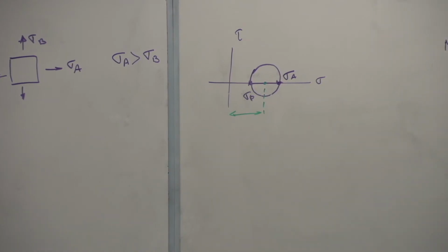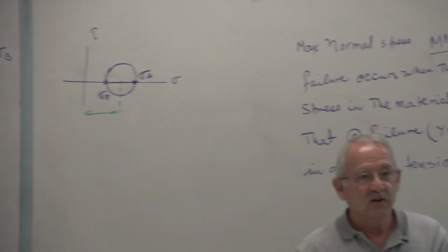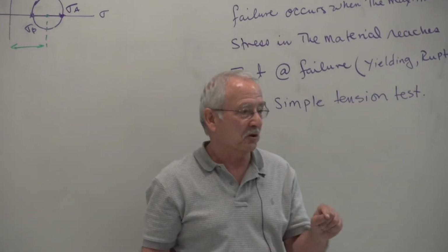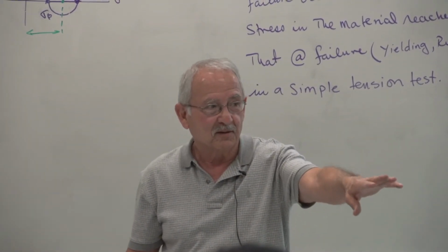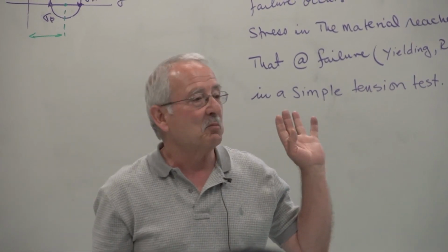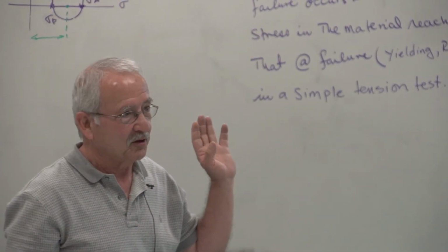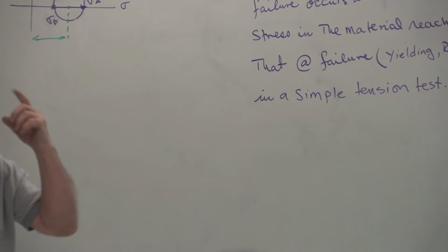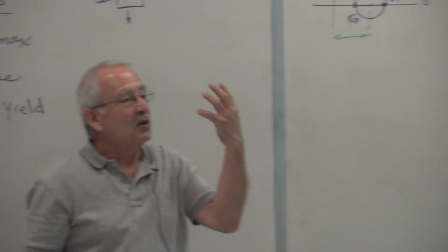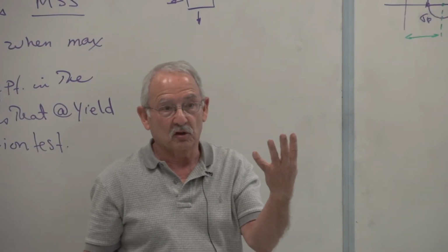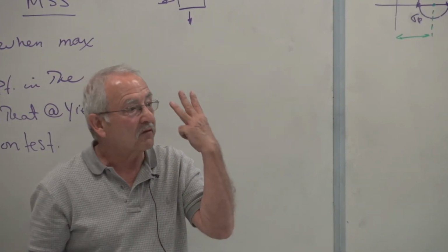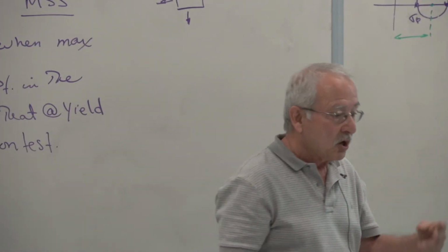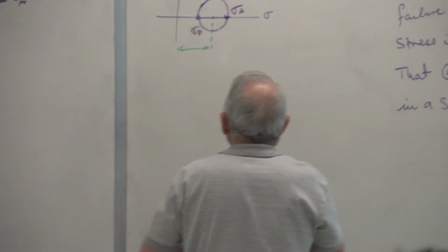One thing you need to get out of is the habit to think two-dimensionally. There's nothing wrong with what you said, by the way. That is the maximum in-plane shear stress. Think three-dimensionally. You don't have two principal stresses. You have three principal stresses. One of them just happens to be 0.